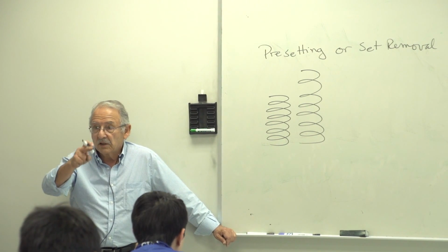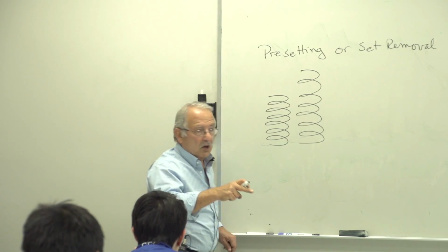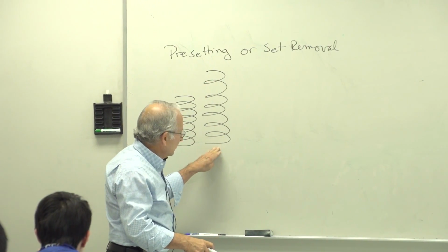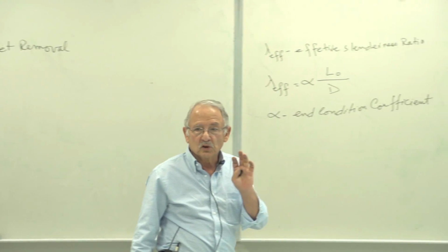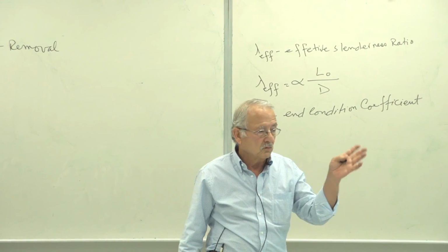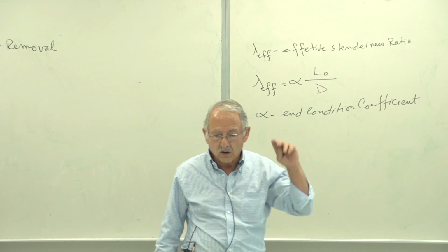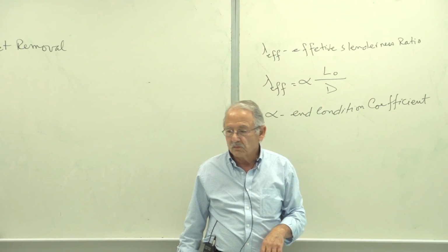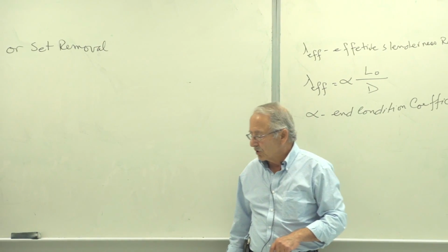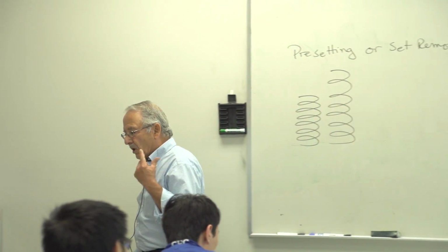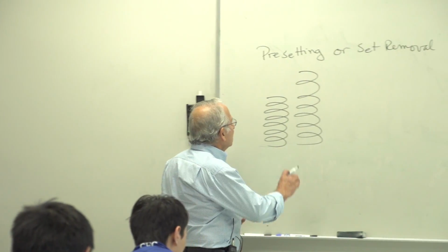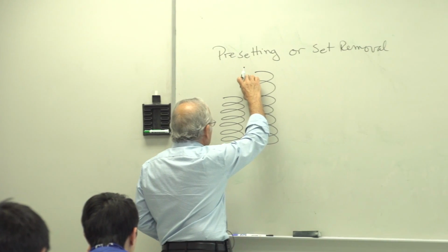In other words, your calculations must be such that if you deflect the spring to its solid height, the spring material will yield. And we have the equations for tau, and you know the yield shear stress for the material. You make sure that tau goes beyond the yield shear stress. How much beyond it depends on the difference between these two.